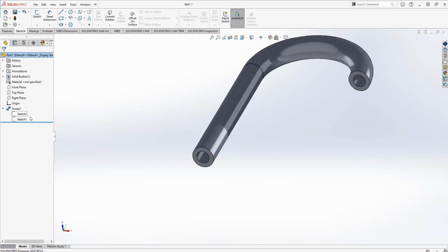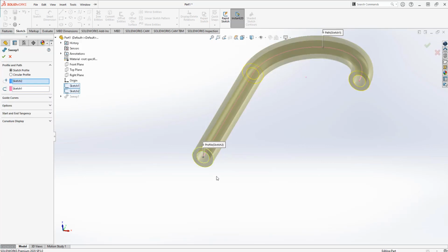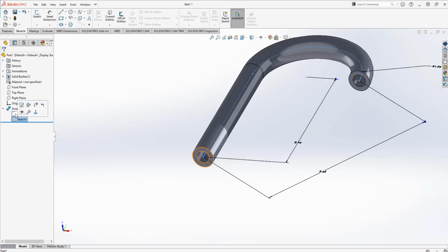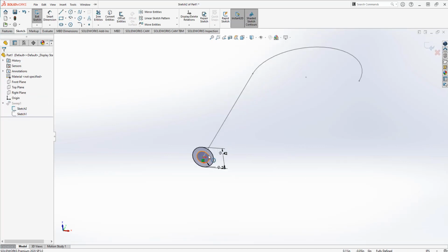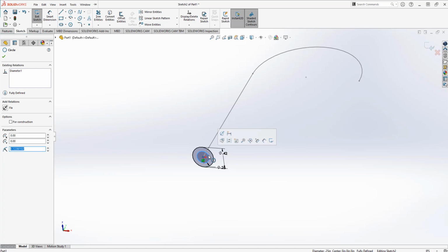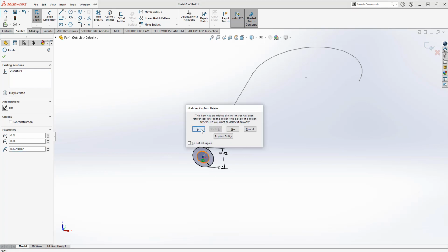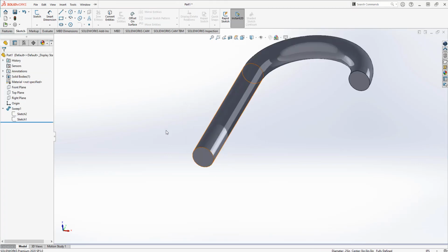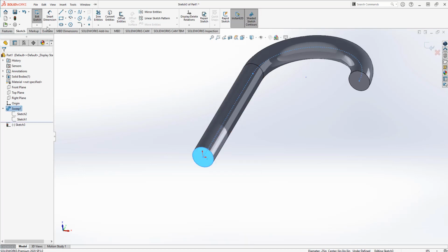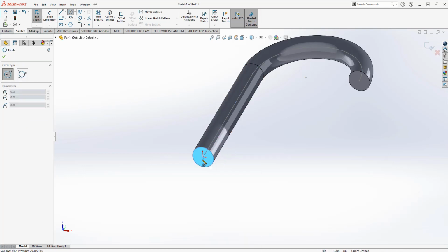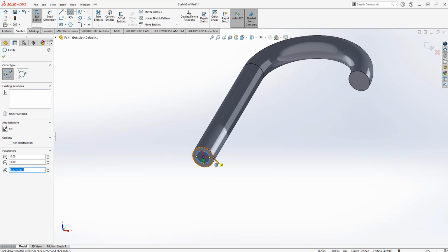All right, I basically use the same one, by creating the profile. But let's say I'm going to go now here. Let's say I get rid of this one. I'll go yes, get out of my sketch, and I'm going to create a sketch on that surface defined by the circle.